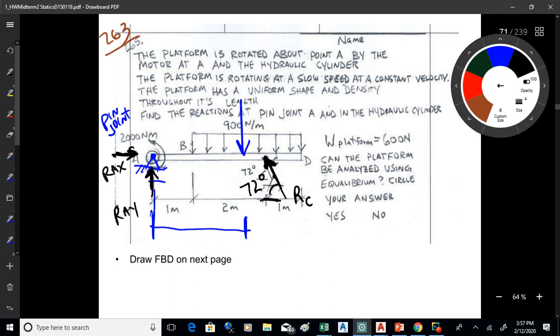So the thing I want to emphasize about making these free body diagrams, again, is don't overthink it. Just look at the connection, put the forces that the connection represents. That's it, okay? Do your deeper thinking later when you solve the problem. So that's kind of the free body diagram right there.